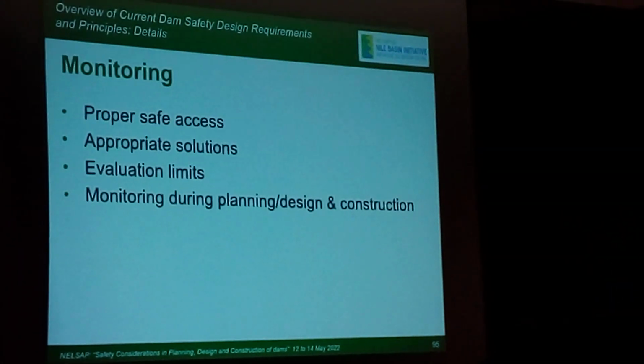In many cases, we can start our monitoring already during planning, especially the meteorological side. Monitoring for me is not just the dam wall. It includes things like rainfall, river flow, because your flood hydrology is your major load on it. So if you can, you should already start monitoring that in planning if you have nothing.